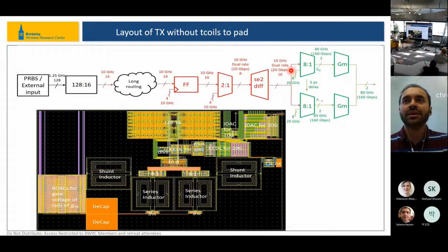So the timing of the signals at this interface is a really crucial thing that we need to look out for. When I'm trying to simulate whether the clock interface is done correctly, I don't really need the serializers in the beginning or the output stage in the end to be present in the simulation. So I just need to make a layout which has everything in this portion over here.